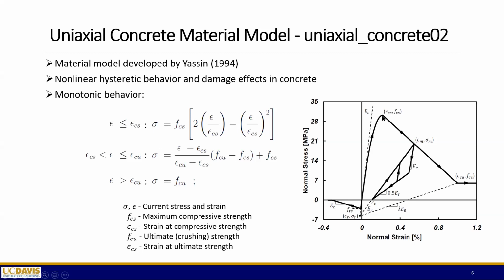And then once you reach the peak stress and you start to rapidly have a decay, then there's another region of your behavior. And when you reach the ultimate strength, the model assumes that you have a constant ultimate strength going on later when you apply even more strains. But for unconfined concrete, you can always put this parameter to be 0, so that you have 0 ultimate strength, which is indicated by most experiments.